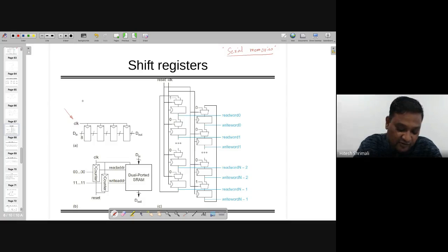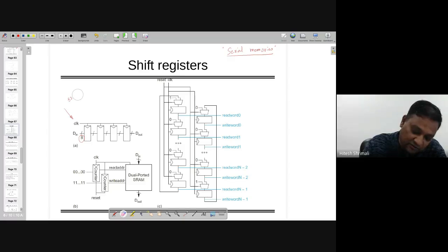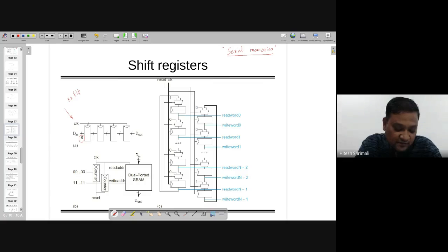And it's plain D flip-flops, and each one of the lines is 8 bits, and this is designed with 32 flip-flops, where each one of the flip-flops is actually 4 bits. So for a bus of 8, you will have a requirement of 32 flip-flops. But this requires lots of flip-flops if you are going for more and more bits.